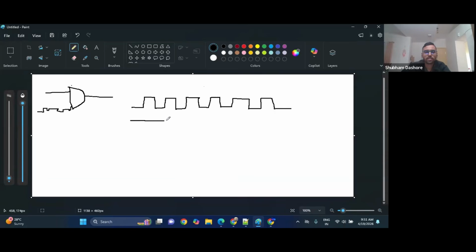And this is the enable, and now we want to do like this. Initially the output of the clock was 0. Now we are enabling it. Then what happens? This will go like this. This is our output clock. Here we can see that for a complete on cycle, our clock is chopped off. It is not one, right? So this is the glitch.